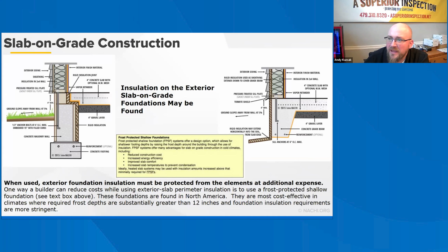workability of wet concrete. Excessive use of water for workability will tend to allow moisture to more readily penetrate the concrete slab, weaken the concrete, and lead to differential drying issues and cracking. Excessive cracking can allow additional moisture as well as radon gas to penetrate more easily through the slab. Concrete control joints may also be used to control random cracking by creating planned lines of weakness in the slab. Shrinkage and curing cracks generally occur in any continuous length of concrete greater than about 12 feet.